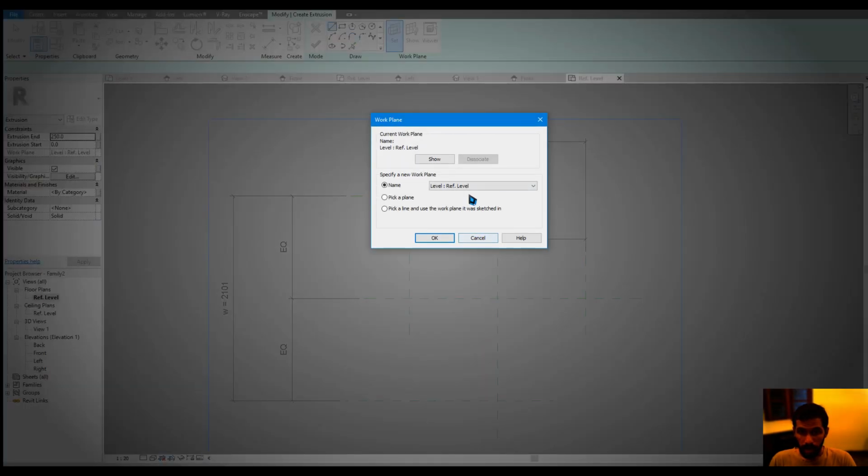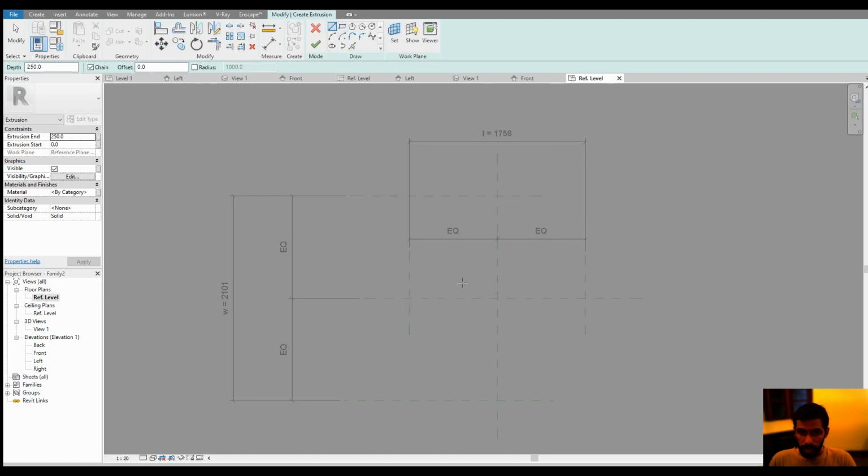Now let's draw the real extrusion. I'm going to set a plane right onto the top plane. You can use any option. I love to use a rectangle here. Rectangle, align and lock it to the reference plane, which is very important. Align and lock with all the planes we have created.